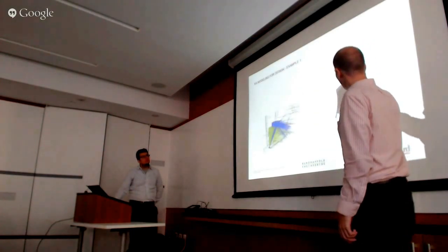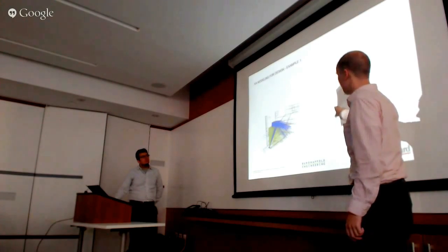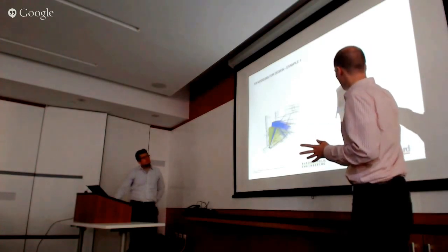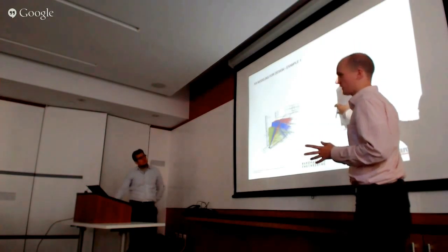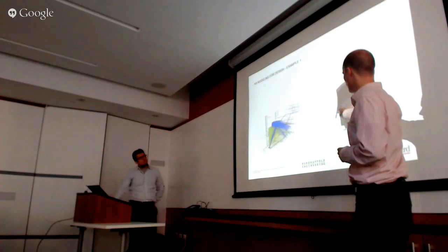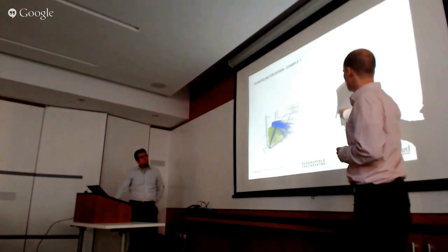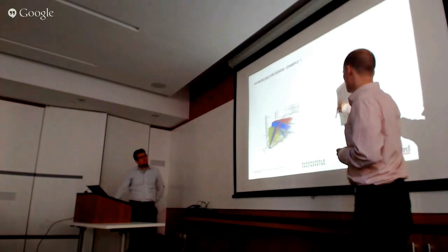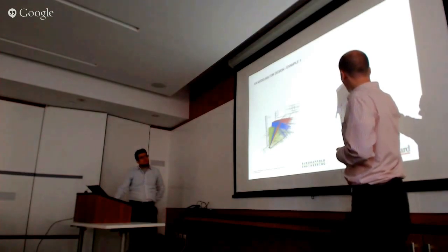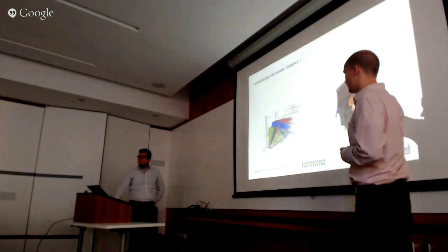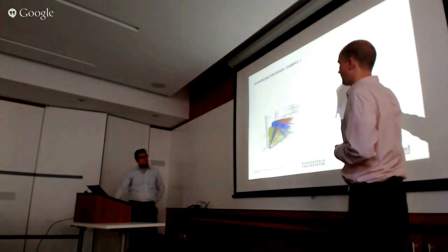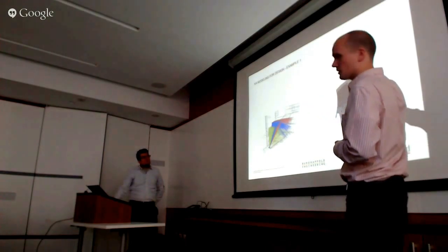So what happens here, as the reflector turns around, it's flatter in the center to give a stronger reflection over this zone, and then becomes more tightly bowed at the edges, so that we make sure that we really treat these areas. If we jump to the next one, this is the first catwalk reflector, which is a completely curved element. One of the things we're really looking at is to make sure that we had good coverage overlap there, while we were still able to flatten this second reflector as much as possible in the middle.